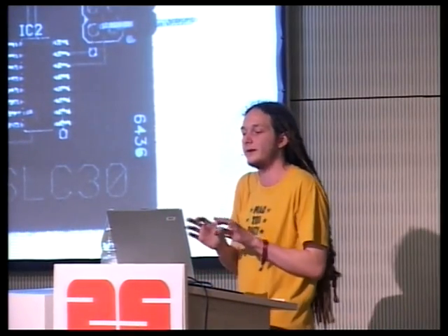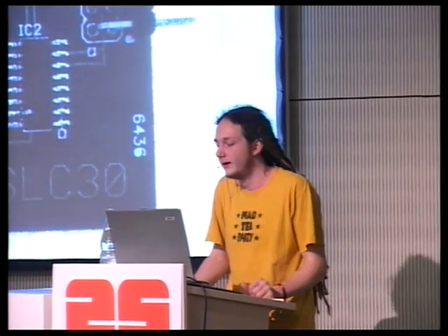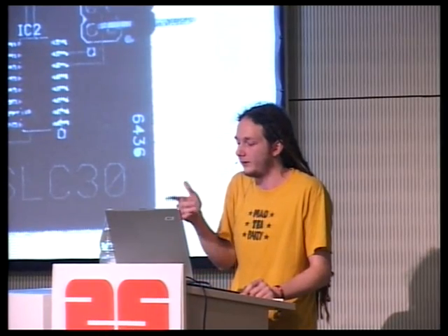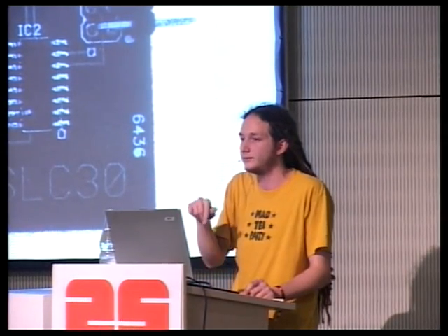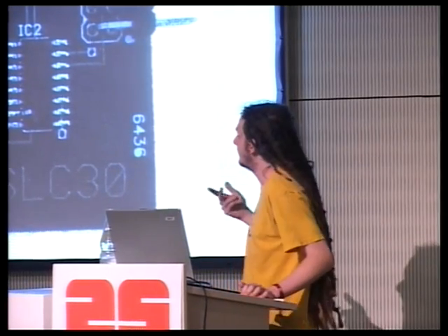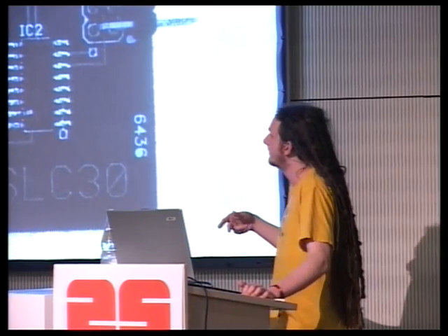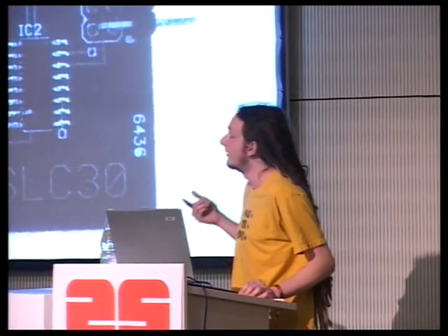At this point, all of the I/O lines are switched to high impedance so that no power can be sucked out of them. And then the voltage line drops to a lower voltage that's controlled by an I/O pin. By use of this, you can glitch past a disabled BSL. With better firmware, you should be able to glitch past the password comparison itself.